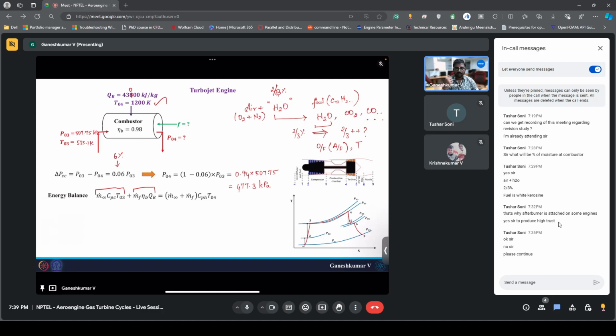But that is actually used for some other purposes. In our case, for aircraft and even for other diesel engines or petrol engines, we always use lower heating values, because our combustion products, we are not condensing at a later point. So we will be using the lower heating value. Okay, so think about it: lower heating value and higher heating value. Why are we using it? What is the difference? Okay, so coming back to the energy balance, the energy with which the air enters is the first term in your equation.